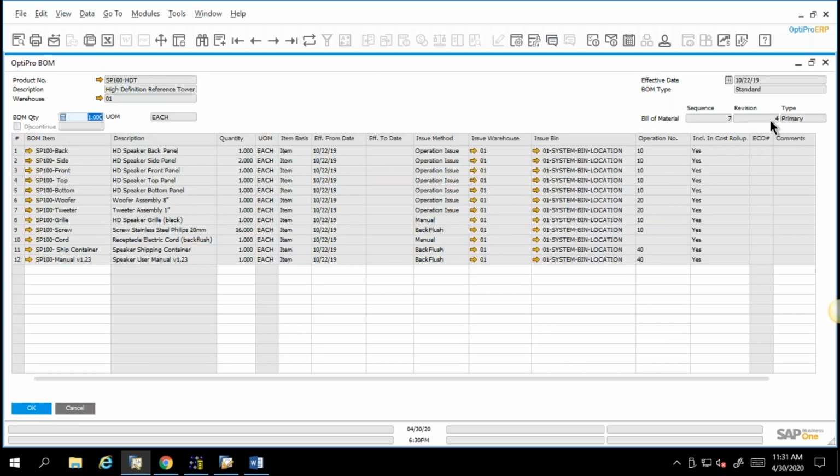So, as I said before, revisions and sequences. Every time you make a change to the bill of material that changes form, fit, or function on an engineering change order, you have a new revision number. Okay, but you might also make more trivial changes that don't change form, fit, or function. It could be even as that you're correcting a spelling error or something like that. There's still nowhere for anybody to hide. Anytime you ever change anything within the system, there's an audit trail placed, and you can see who changed what when and what did they do.